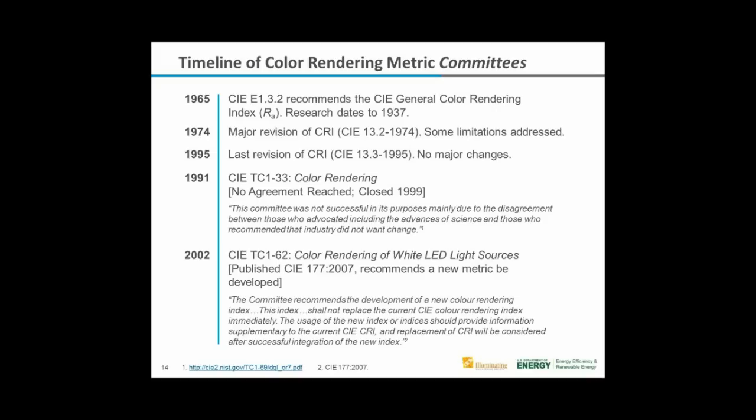I think this is kind of interesting because in a way we've been in this situation for 24 years and are still a little bit in this situation where there's many people out there who would say it's too much work to change from CRI. Well, I hope today and in your time you learn about TM-30, you realize that the advances in science really do provide a highly substantial advantage over the previous methods, and it's really worth any kind of effort to make that upgrade.